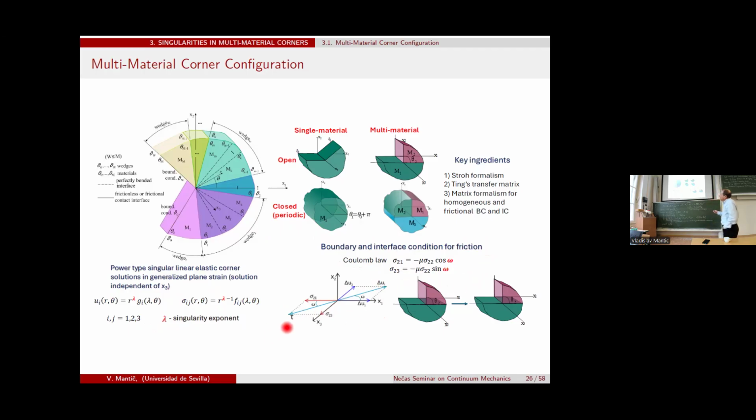We consider here isotropic friction, although the theory is developed for an anisotropic friction model, where you can have an isotropic material, but using an anisotropic friction model, because in some situations you may need it, where we don't have, let's say, parallel shear stress vector and relative displacement vector in the contact zone. So the theory is prepared more general, but our code, because there's no demand at the moment, is just for isotropic friction model.